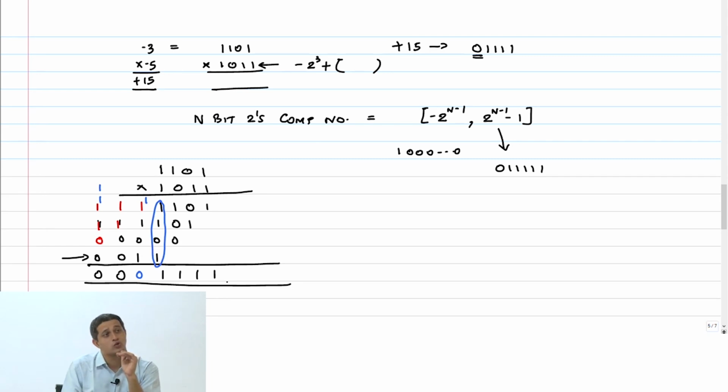The arithmetic should be such that how many ever bits I sign extend, I still get that answer. Previously we said we have to drop that carry. That is not correct. The carry is going to be used in order to allow this sign extension to as many bits as you want.